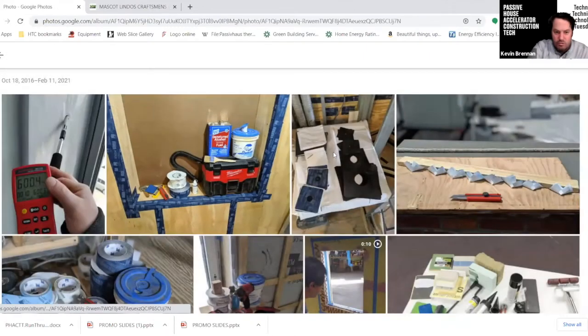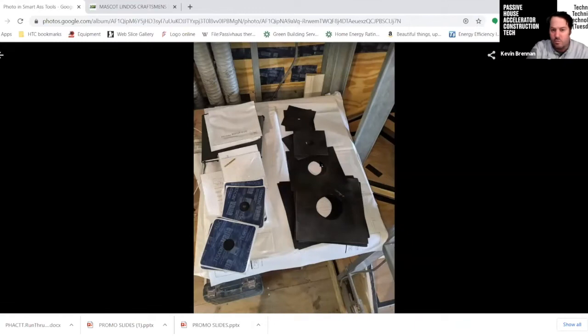The next set of tools are all the tricks in the tool book, right? On-site labor is expensive and it takes time. So if you give these little grommets and gaskets to the general contractor team that is allowing people to do work in certain areas, they are going to put them on the pipes and the electric penetrations, and then they leave them for you to set up. It also acts as a really good guide for whoever you're handing them to: just make sure there's enough space so that he can tape it on the other side.